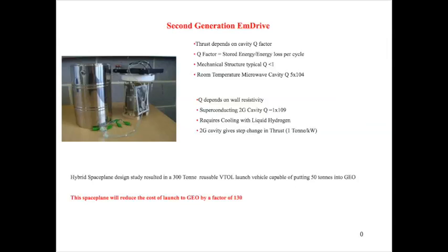There's a big advantage in this because using liquid hydrogen to cool the cavity means that as you boil off the liquid hydrogen, you can make use of the hydrogen gas in a fuel cell along with a bit of oxygen to produce your electrical power. And in the early designs of spaceplanes, you can see that the hydrogen is also used for auxiliary propulsion.